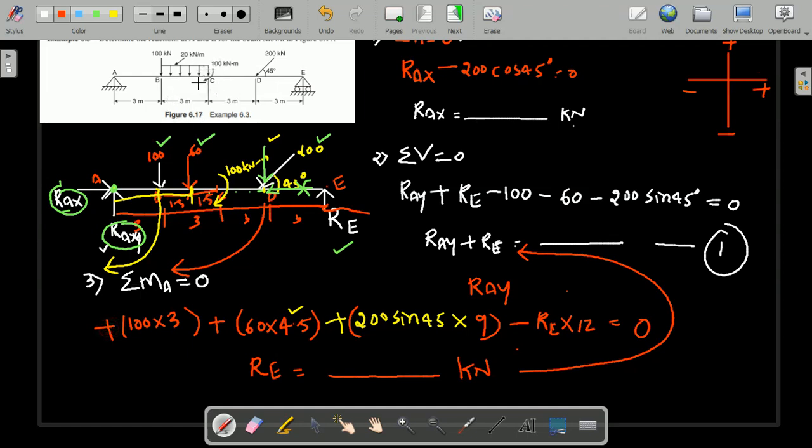Because at the C point the moment is given here, and it is a clockwise moment, therefore plus 100 you need to add. So if a moment is given, while calculating the summation of moment equal to 0, you need to add the given moment also. Then you need to simplify, and you will get the support reactions.